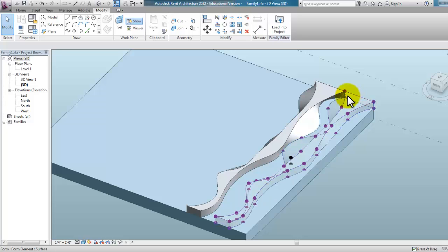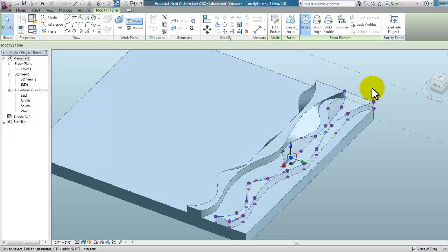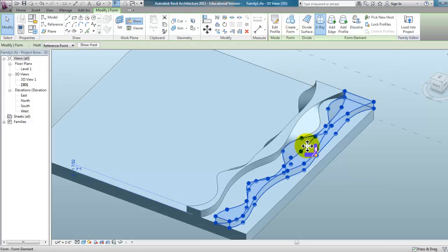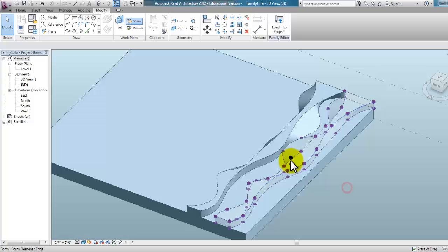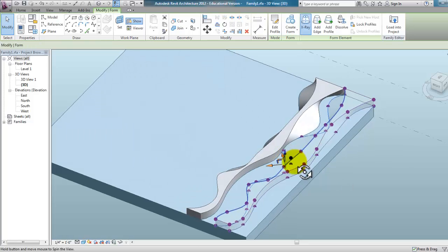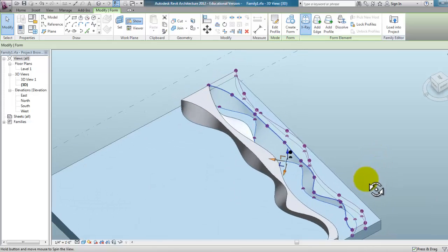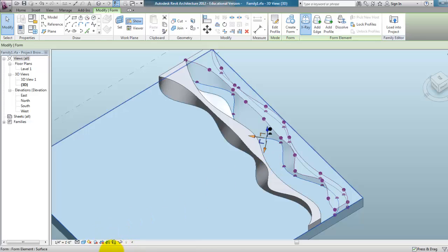save that shape. Here I'm also able to tab over to the top surface and go through that same process. You can pick Edit Profile and start to modify that curved shape. And I noticed that in the one that we're trying to create, we want in some cases the top to be smaller and the bottom to be wider, and some other times we want it to be wider at the top and smaller at the bottom. So this gives you the flexibility of editing both faces.